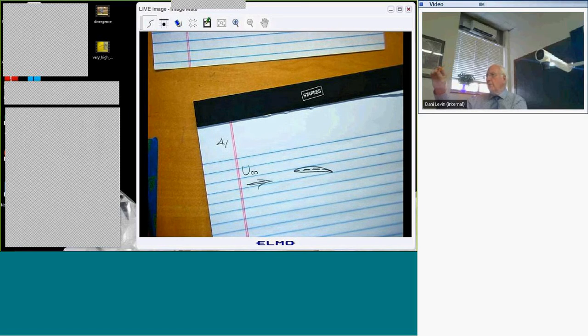What really happens is, in classical flow, we're basically assuming that the mean flow can be approximated by just U infinity. It's just a nice uniform flow, and we're doing a perturbation about that. In transonic flow, we really need to allow for the fact that the steady flow is changed from the free stream flow by the thickness of the airfoil and by any mean angle of attack before we begin to oscillate.